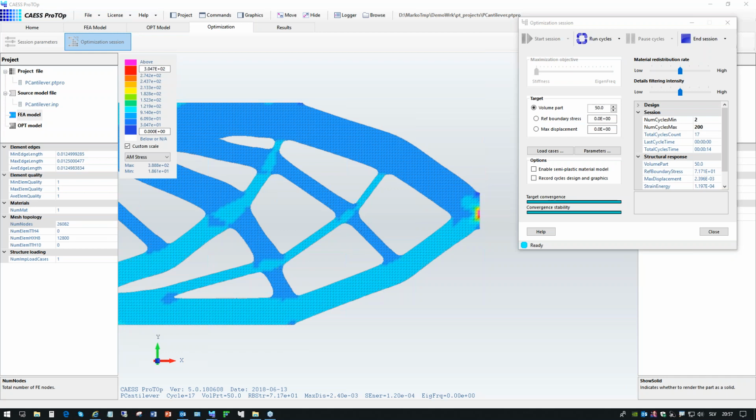So you have to model concrete, even reinforced concrete, as a homogeneous material, if this is possible or acceptable for you. And what you can do regarding this tension and compression is what I have already shown. So you can require that the stresses in the tension region will be lower than the stresses in the compression region. I hope this answered number 3.